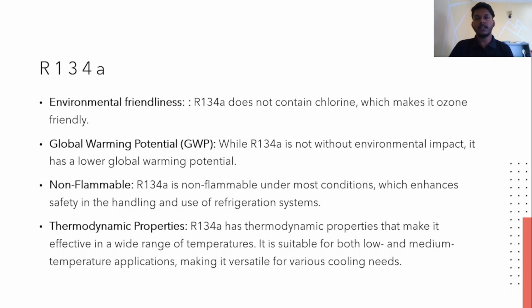R134A. The advantages of R134A is environmental friendliness. R134A does not contain chlorine, which makes it ozone friendly. Next is global warming potential, GWP. While R134A is not without environmental impact, it has a lower global warming potential. It is non-flammable under most conditions, which enhances safety in the handling and use of the refrigeration system.